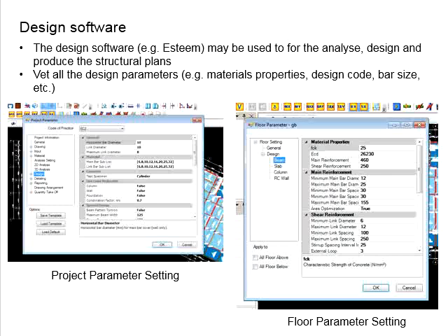In the case that any members fail, the software should notify you. You will have to do numerous tries until all the members pass. There will be a lot of trial and error. Whenever you make modifications to the key plan, there will be analysis, the load will be distributed, and there will be design. The amount of reinforcement bar is proposed. If a member fails, the software will notify you and you know which member you should modify to improve it. The entire process requires extensive technical knowledge as well as industrial experience.